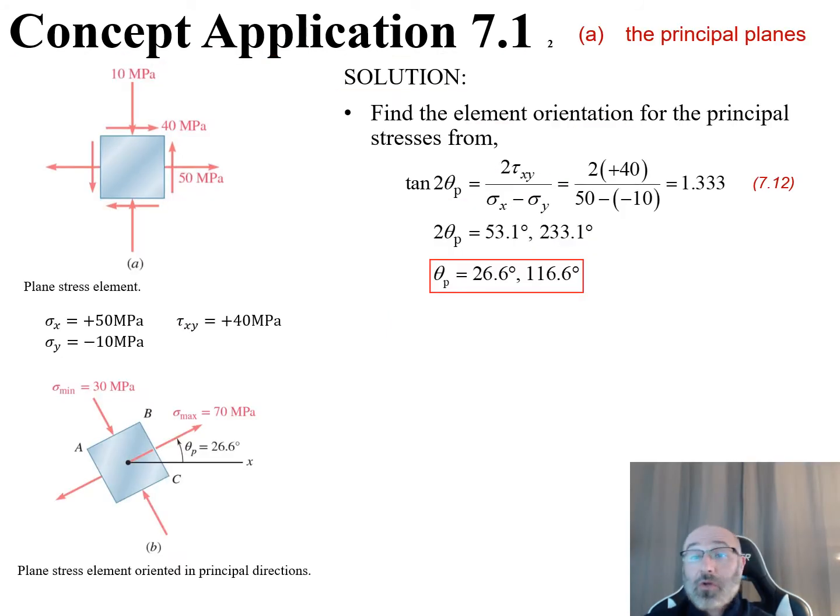So now that we've had the opportunity to read through that problem statement and take a look at our initial given diagram, we have all the information we need to create our setup page. If we were solving this problem by hand, we'd create that setup page. We take all that information from the diagram and problem statement and write out everything that's given to us in one section. Then below that, write out everything we're asked to solve for. And we want to include any given coordinate systems and any assumptions we're making as well. This will be the page we can reference back to and utilize to determine our governing equation.